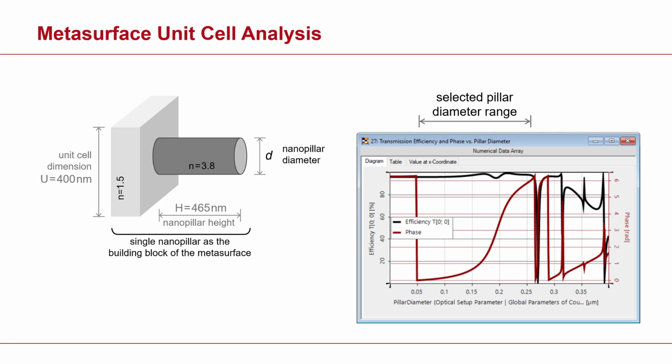with the pillar diameter range, and we do so in a way that guarantees an aspect ratio of the pillars that will not cause many problems, or that is reasonable, so to speak, from a fabrication point of view. So knowing the materials we're going to use, their refractive indices, we select a pillar height and a pillar diameter range to investigate. That provides a reasonable aspect ratio for the pillars. This part of the design process is a bit glossed over, but that is how we get to that pillar height that is already fixed there.